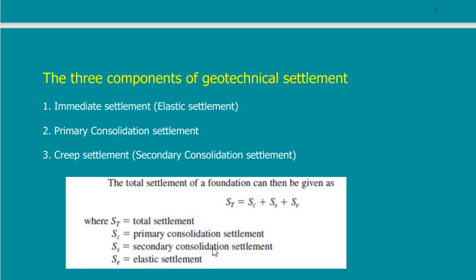It has nothing to do with consolidation, and it is only because of the change in the shape of the particles itself. In all types of consolidation, we are speaking about the voids. The voids are decreasing and expelling water, or decreasing and expelling air. Decreasing and expelling water, it's consolidation. Decreasing and expelling air, it is immediate settlement.